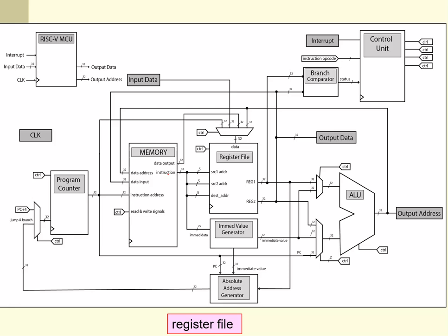Next, we have the register file. This is the register file right here. If you remember correctly, we have stuff like add x10, x11, x12. Essentially, it's reading data from two registers and writing to another register. What you're going to find here is that it is a piece of memory, a special type of memory, which is referred to as a dual port RAM.